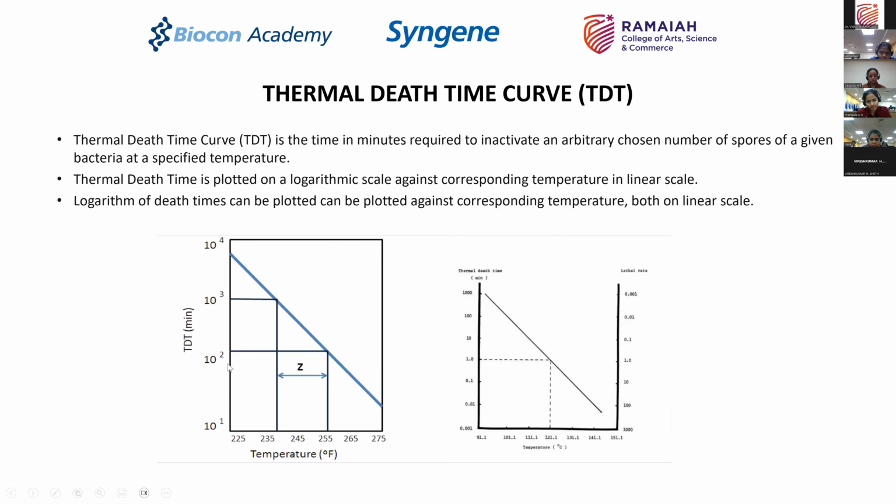Okay, so by changing the temperature, I'm going to be able to determine where I get that additional 1 log reduction by change of temperature. So I was at 235 degree Fahrenheit or let's say 121 degree centigrade, and I changed the temperature to 130, 131, and wherever I get this 1 log reduction on the lethality or the surviving organism, I know that by changing the temperature by 10 degrees centigrade, I am able to get a 1 log reduction quickly.